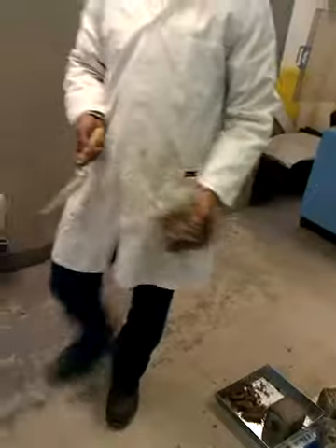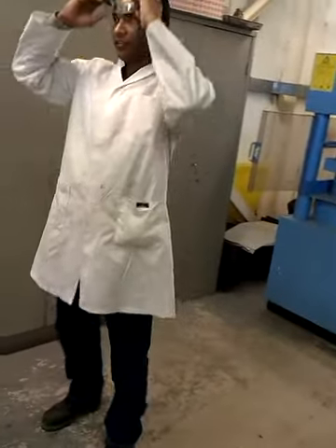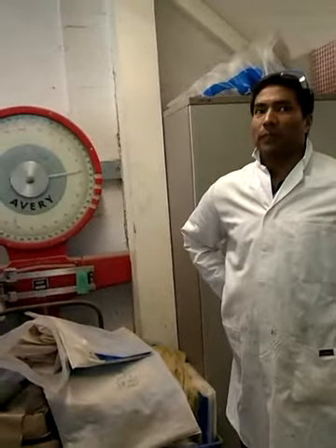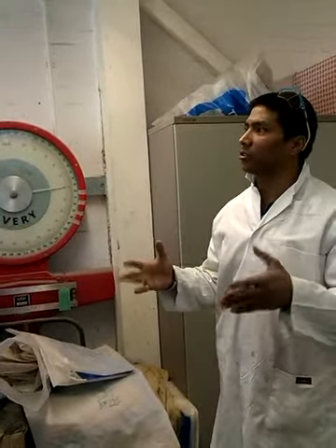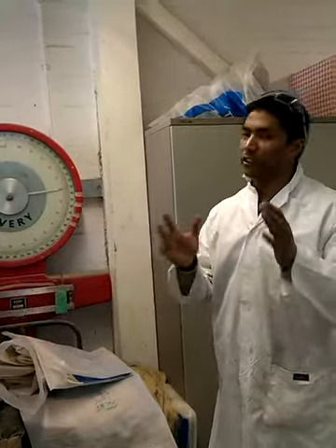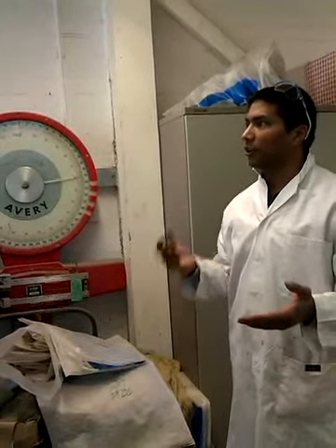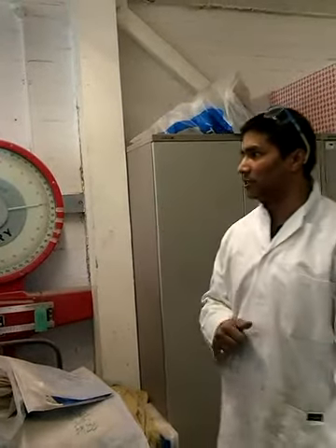Okay, any questions, Shafar? No. That is all about the destructive and non-destructive test of the concrete. So if they are both used in conjunction, then you would use the non-destructive first, and then you would. Not necessarily. Sometimes you need to test the concrete only non-destructively. You don't want to destroy the concrete. In that case, you're going to do the NDT test. But after all, the effective strength will be achieved by compressive strength, that is after 28 days.